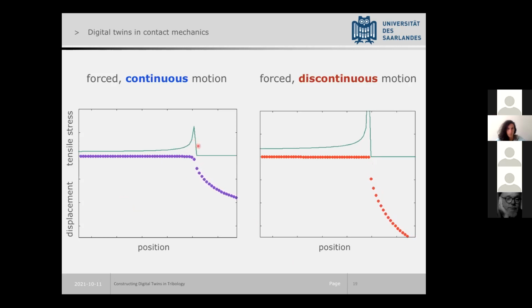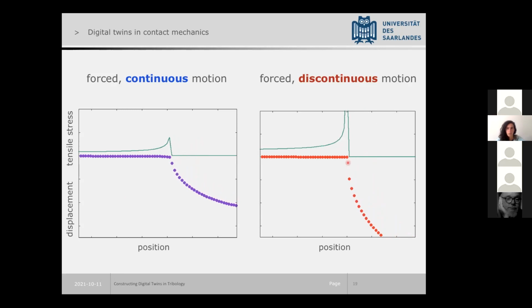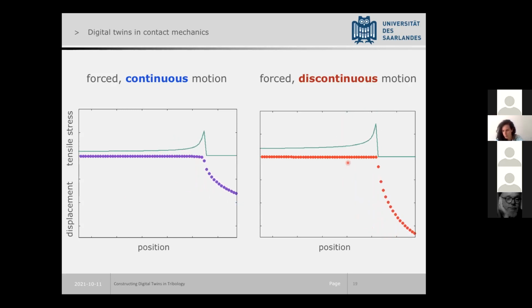a propagating crack front, where you see here each point actually always has one well-defined stable position, which it tries to reach. And here, when you're discontinuous, a minimum that was stable in the past all of a sudden becomes unstable, and you have a discontinuous change to a new position, which then basically leads to a different law, and which means you get much, much greater adhesion.